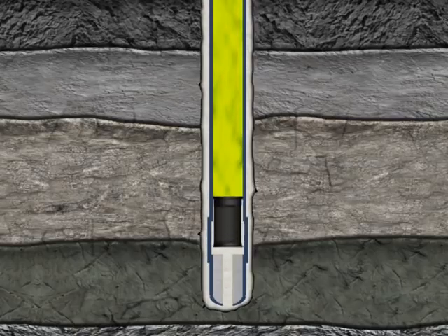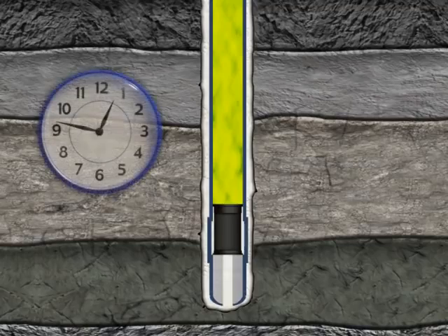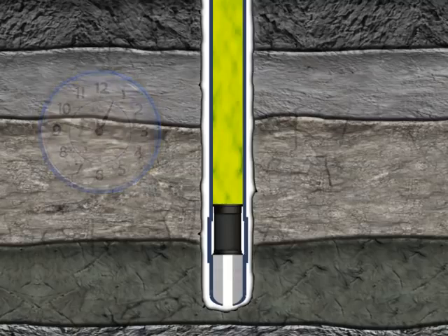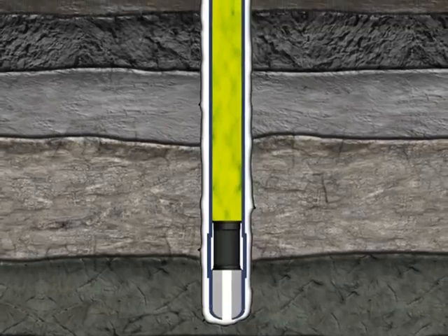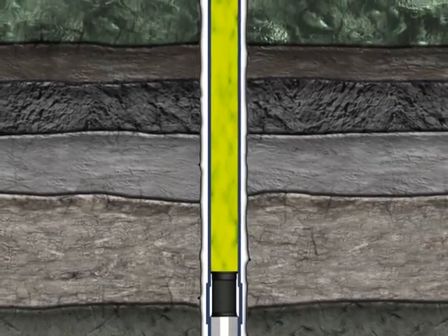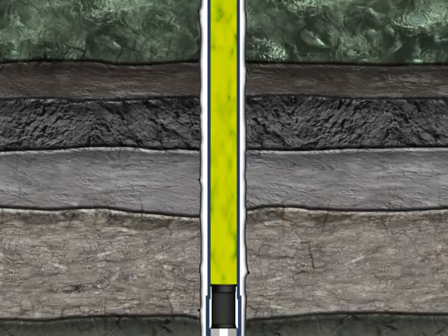To allow further operations in the well, the cement requires sufficient curing time. The cementing process is not always a flawless operation, and the resulting cementing job might contain some bonding issues that would undermine the strength and integrity of the casing, especially during perforation.